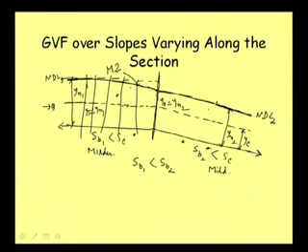In this case, however, the profile is not moving to the critical depth line, because the depth is not coming down to the critical depth. This depth is governed by the flow here, and the depth is this much. So it is never coming to this point, it cannot come to this point.